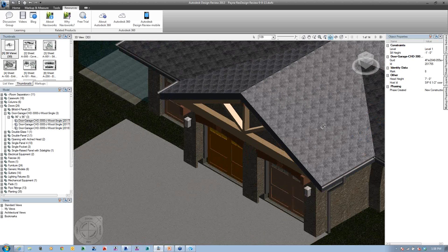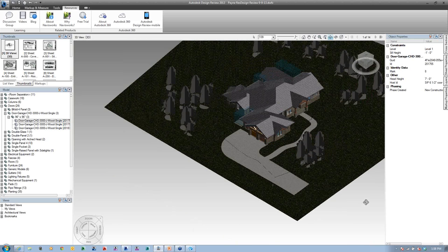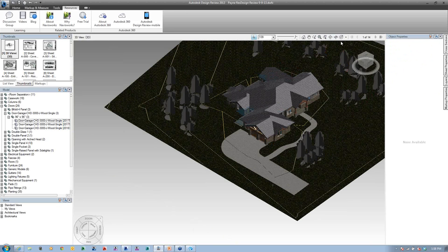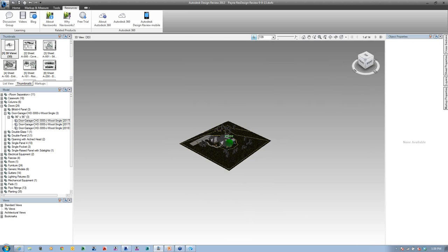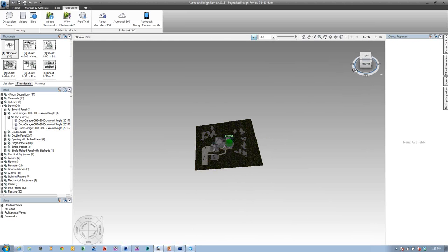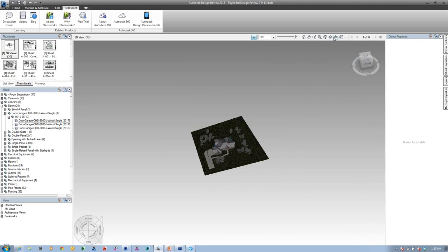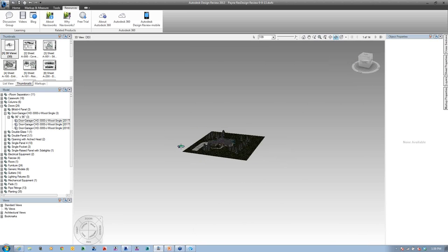And I've got that door selected, and that's why I focused in on that garage door. If I go in and unselect it, by just going in and unselecting, I've got nothing selected. Now I come back in here, and I can go to that cube, zoom out, or rotate by using the cube as we're used to. The other thing we have is the turntable down here, which is kind of nice. Or we've got this turntable here, and I like using this one a little bit better. It's more like Revit Orbit. It tries to keep the orientation correct.